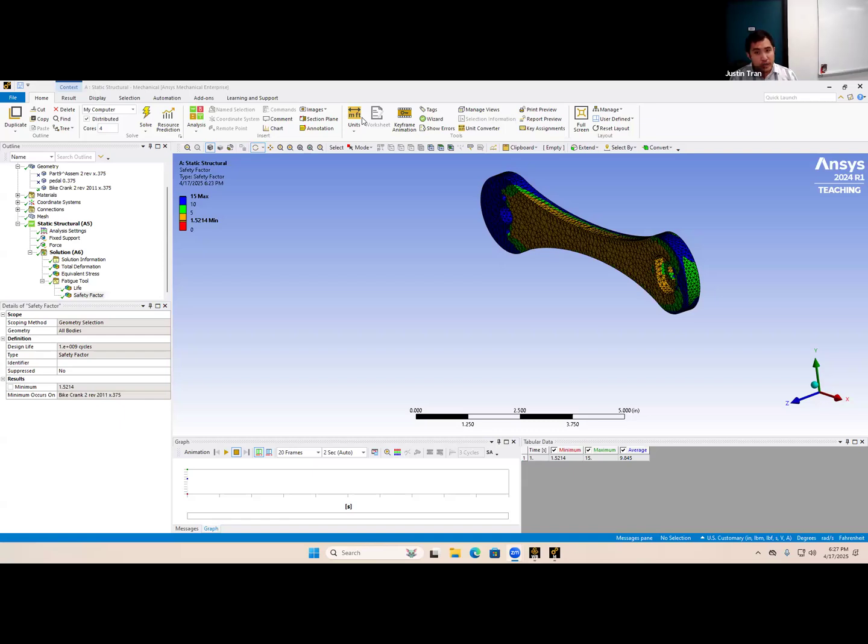People have actually had success doing shell and beam elements. I think someone did shell elements for the 4-way valve. They were quite successful with that, so I would definitely try. I do know that ANSYS does typically struggle when you are doing a shell element where the thickness varies. That usually happens when you have curved parts. The thickness will be fairly consistent in certain parts, but when the valve merges together with other parts, the thickness can be a little bit thicker.